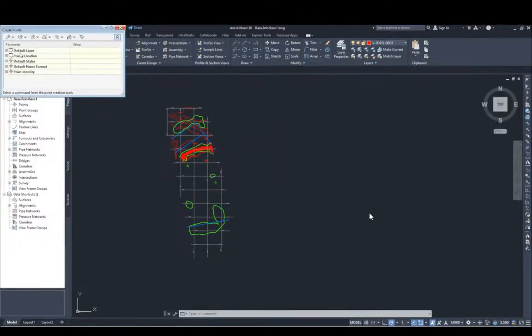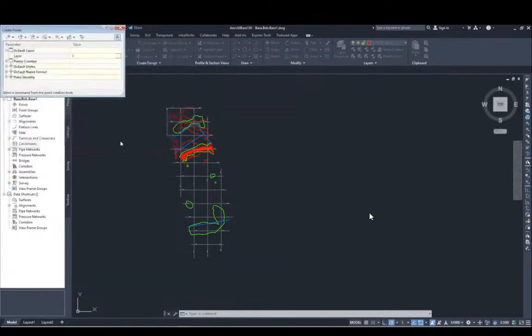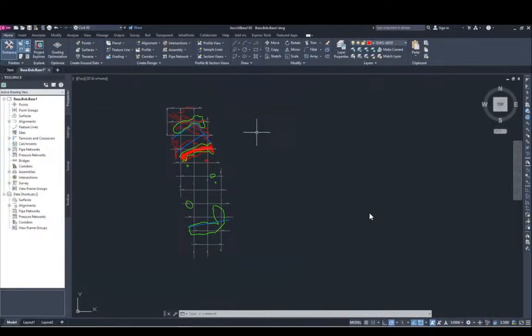And we're going to change the default layer. That's what we're going to change here. So you can see the default layer, when we import some points now to our drawing, the default layer that it goes to is layer 0. And I don't want that. I want it to be that current layer that we just created. So I'm just going to click that, click the dots on the side. And then I'm just going to go to the very bottom here. And you're going to use current. That one that says use current, we're going to hit OK. So it's set for use current. Once you have that, you can close this. And there we have it.